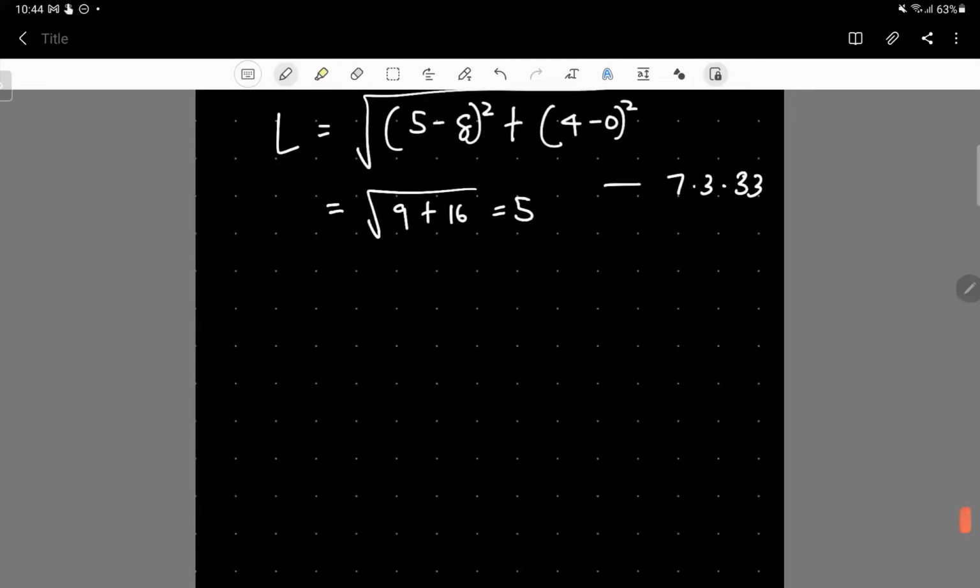We already know that since we are dealing with node number 2 and node number 3, the shape functions N2 and N3 must be used for evaluating the surface traction forces along the side 2, 3. The edge 2, 3 corresponds, in terms of the natural coordinate system, to S is equal to 1.